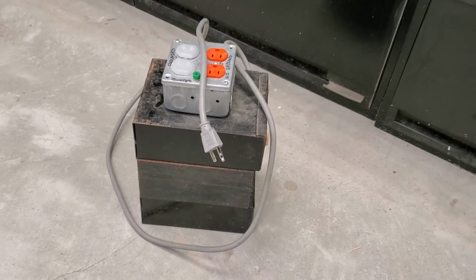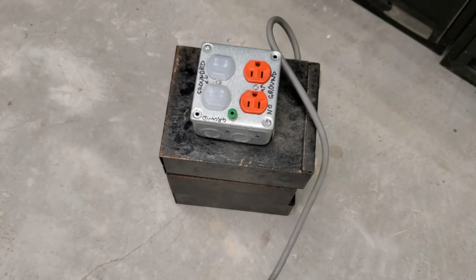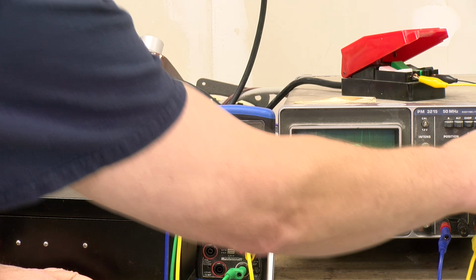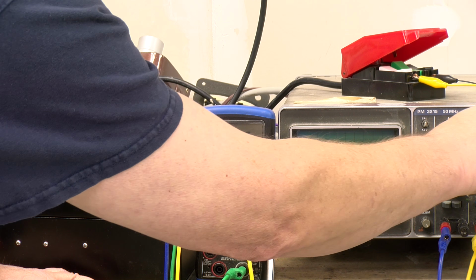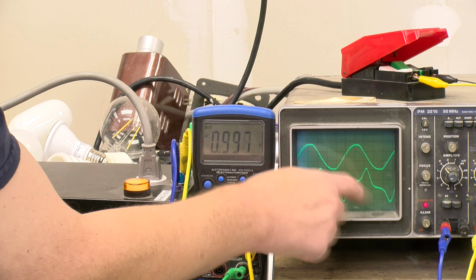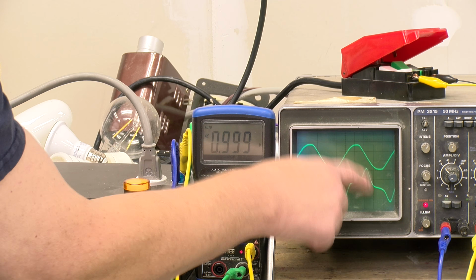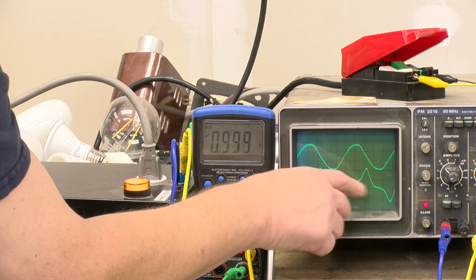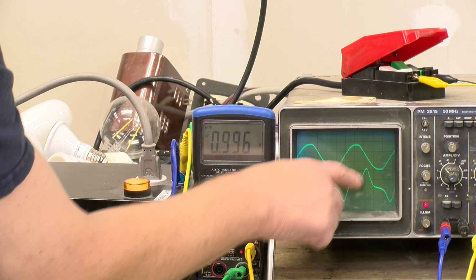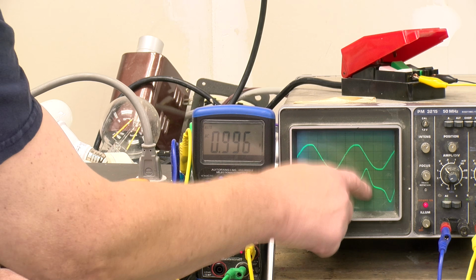And I have my great big isolation transformer. This is a kilowatt type transformer. And if we plug it in here, what do we get? Well, we get, and we've seen this in previous videos, a waveform that shows when we get close to the peak of the current because of saturation in the core, and we're moving up the BH curve. As it gets more saturated, we need more and more current to achieve the required magnetic field, so we get these peaks. So something like this does produce some harmonic.